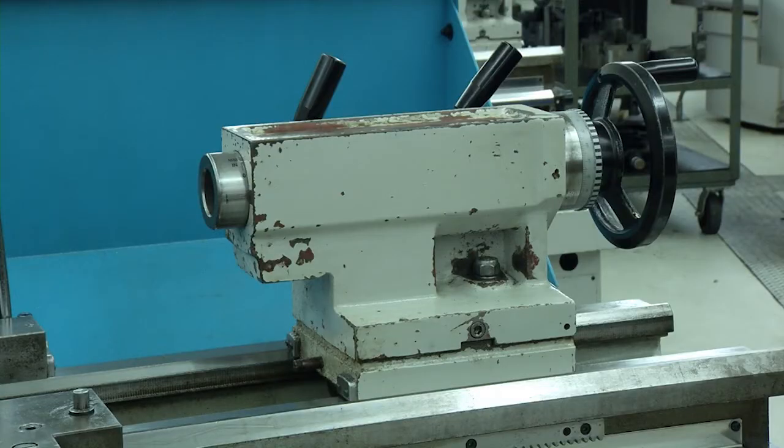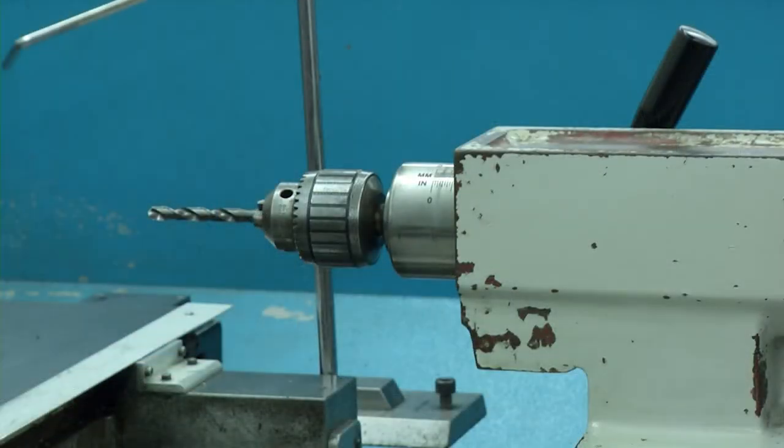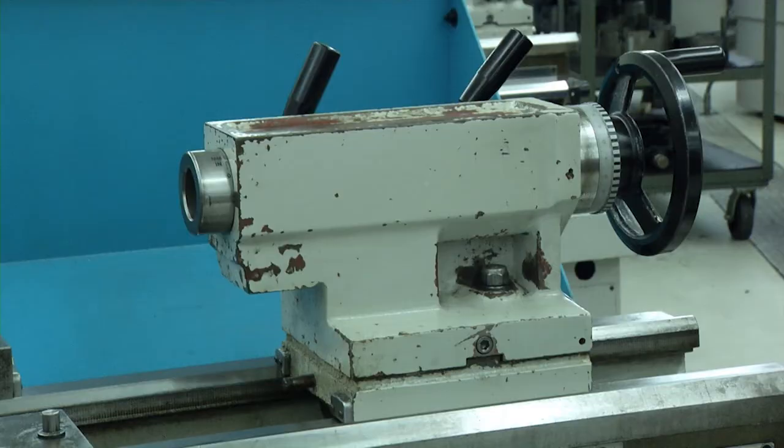The tailstock supports the right end of the work. The tailstock also holds tools for machining operations such as drilling, reaming, and tapping. The tailstock is made up of a 2-piece casting. The lower part, the base, clamps to the ways. You can adjust the upper part using the set screw. Adjustments can be made to turn slight tapers or for aligning the tailstock to the headstock.